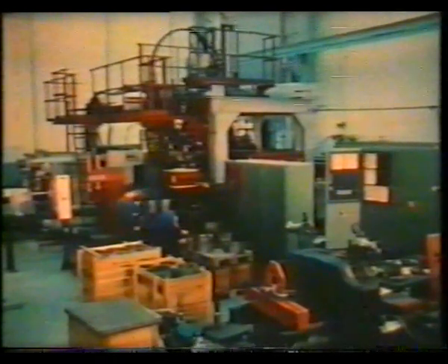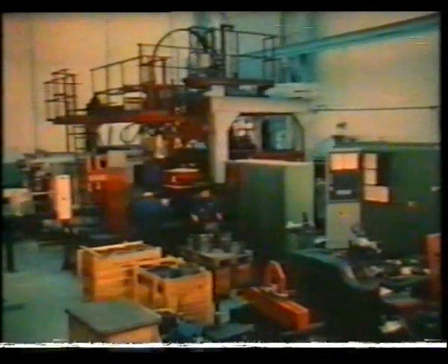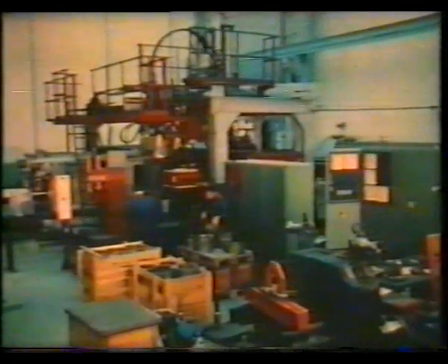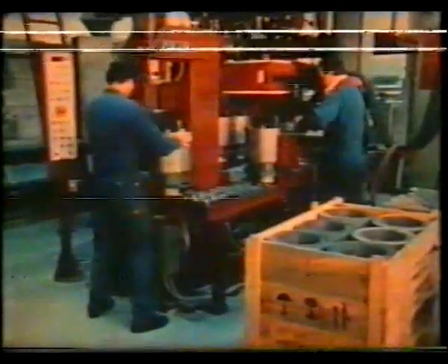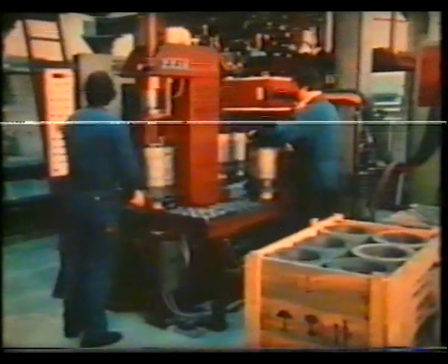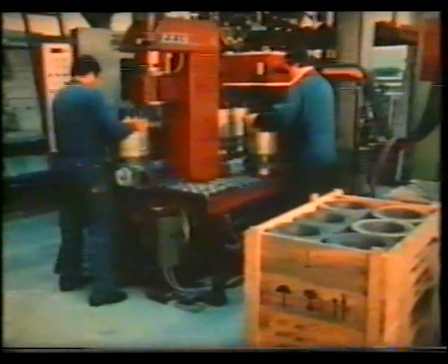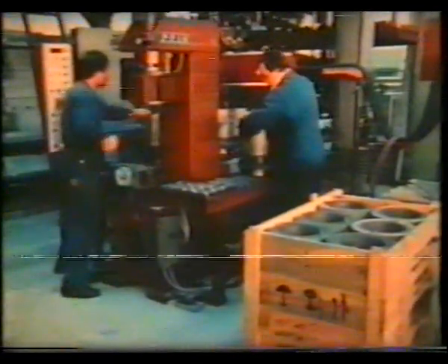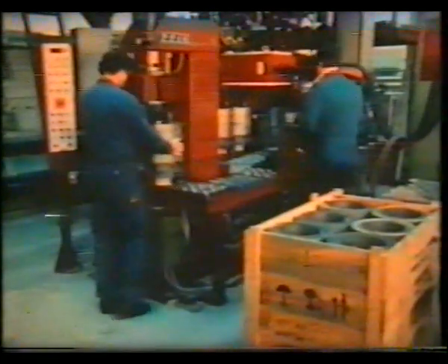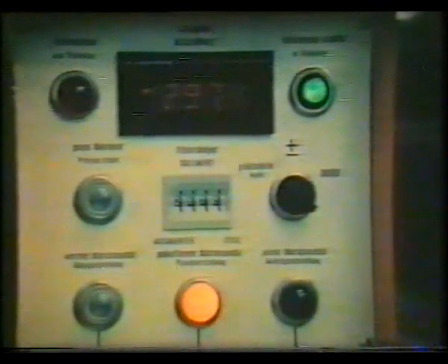The vital element of the system is the die casting machine with 15,000 kilonewtons locking force. The process includes the preparation of the laminar stacks and the casting of the stator housing. In the pre-stacking station, the stator lamellae are stacked by hand on positioning plates and then checked under pressure for proper height in the stacking machine.